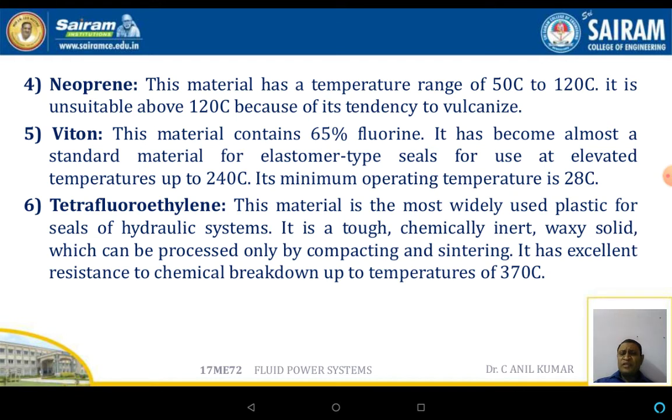Neoprene. This is a material with a temperature range somewhere around minus 50 degrees to 120 degrees centigrade, and it is unsuitable above 120 degrees centigrade because of its tendency to vulcanize.